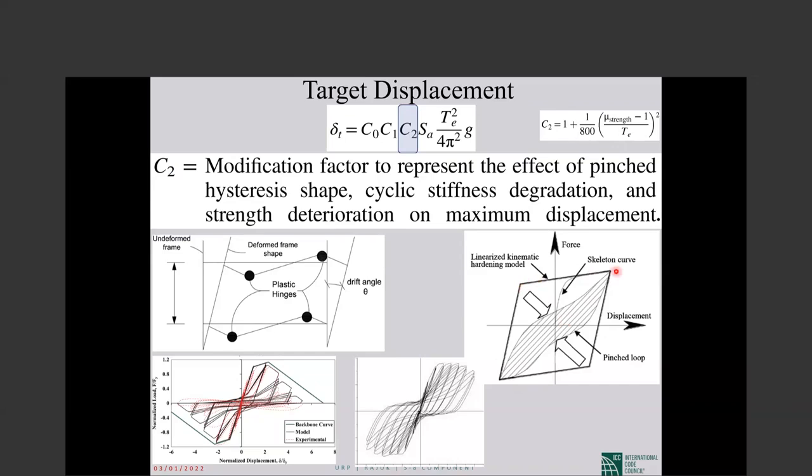If after a couple of cycles the load-deformation hysteresis curve of those plastic hinges pinches and the area reduces, the capacity of absorbing decreases.